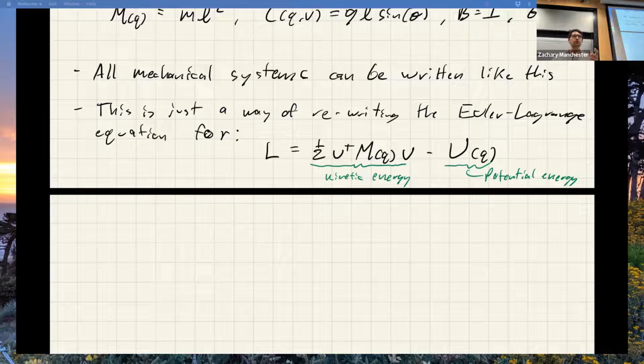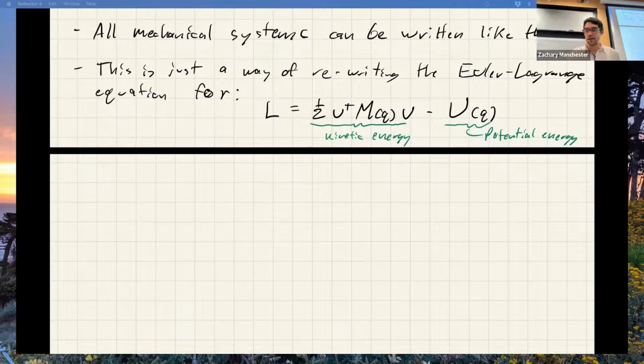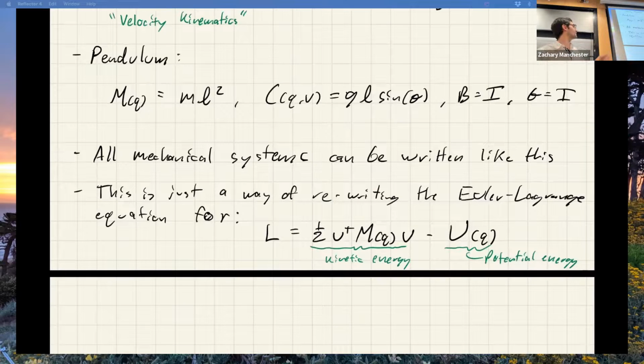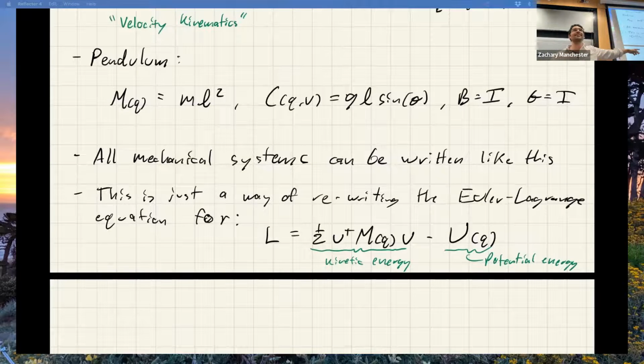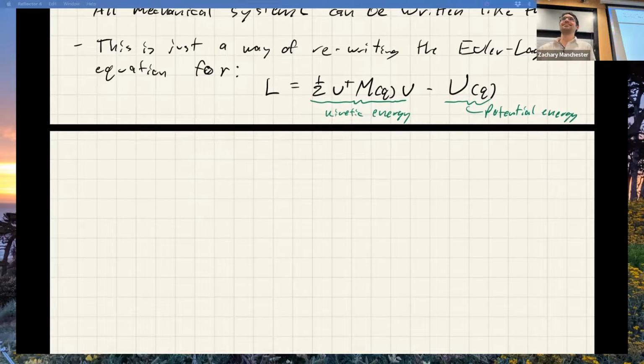In the special case where you're in R3 with a point mass and it's Cartesian, it is F equals MA, exactly. But in the general case, it's a lot more complicated. The generalized coordinates, your Q's, are the key thing. If anyone wants to show how to get the manipulator equation from that Lagrangian, bonus points. It's kind of fun and slightly non-trivial. You need to think about tensors to do it.